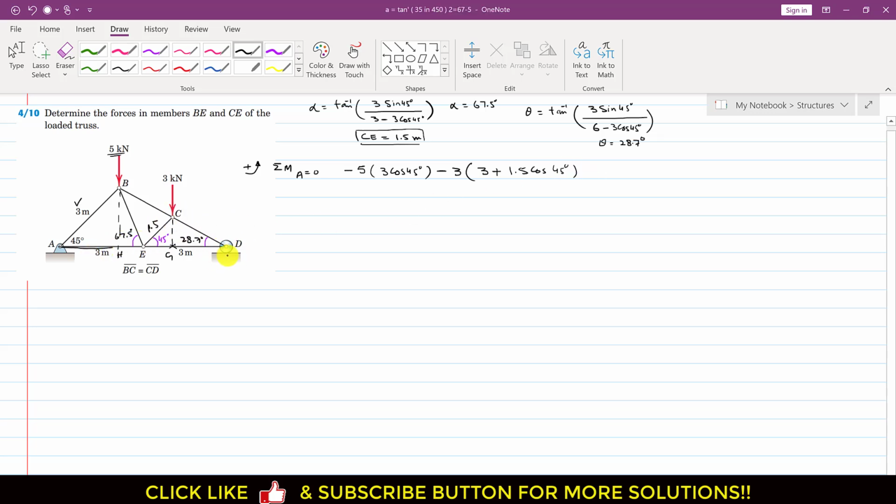We haven't represented the reactions at points A and D. Since this is a roller reaction, there will be a reaction in this direction at point D. This will be, let's say, Dy, and there will be two reactions at point A. Since it's a pin joint, there will be a y reaction, AY, and one reaction AX, right? And we represent this as our positive x and positive y direction.